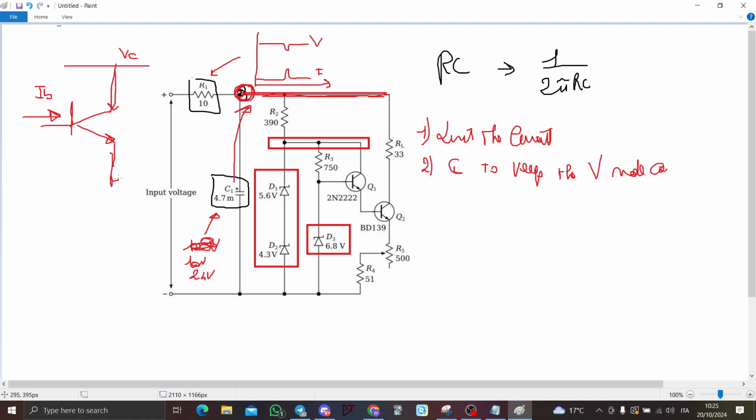and then the current will flow in this direction here. Now, in order to make this diode work, you have to polarize this diode with a current which is flowing from the power supply. Hence, you need this resistor R2 to make the current flow into this diode here, and then we'll have a few milliamps, a very low current to give this boost of voltage and give a constant VC. So this Q1 is okay.